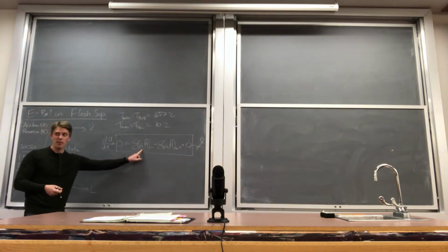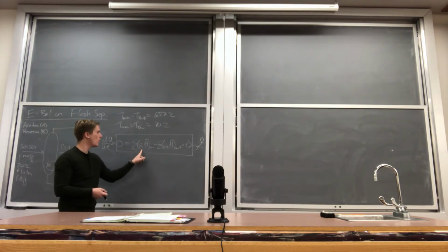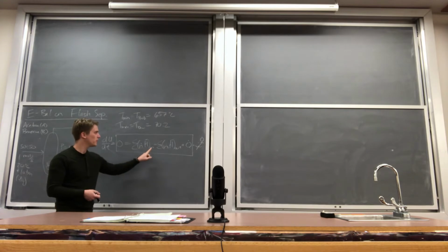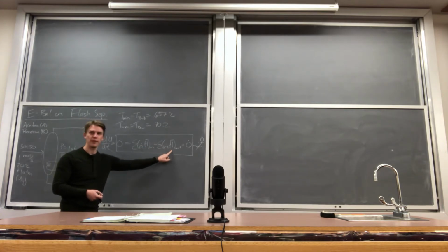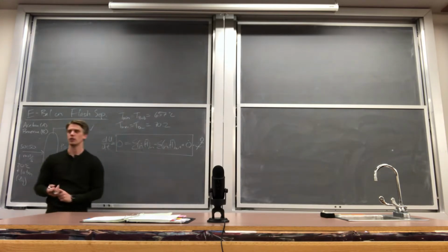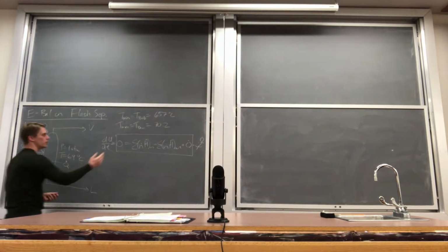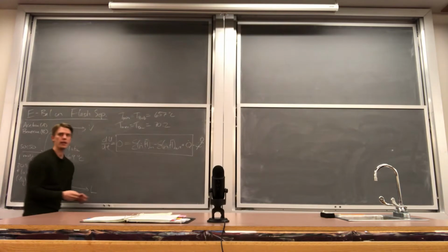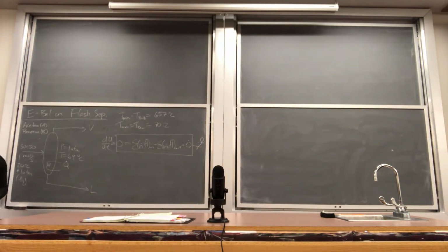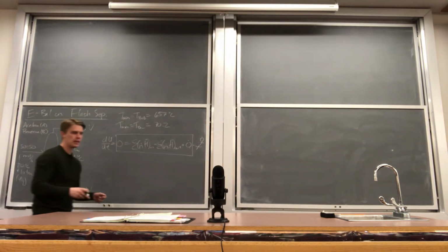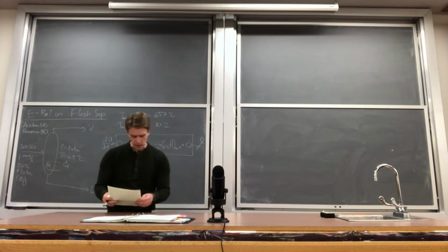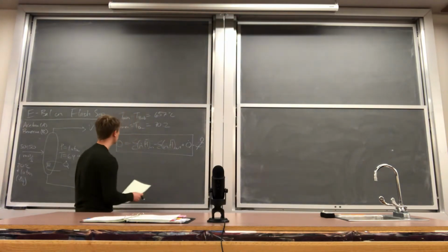We know some of the molar flow rates, right? We know the inlet conditions, 50-50. We know all the inflow rates, but we don't know their enthalpies, we don't know the outlet flow rates, we don't know their enthalpies, and we don't know Q. So it turns out we don't know a whole lot of information about this problem. But the first step was to solve for the flow rates and balance this out as a normal flash calculation. So let's work on that part.